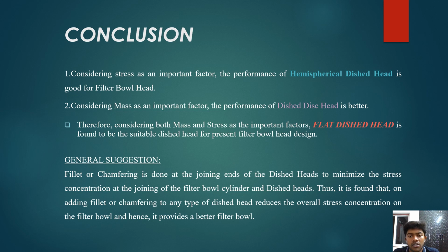So the general suggestion which can be given based on the conclusion above is that filleting or chamfering is done at the joining ends of the dish head to minimize the stress concentration at the joining of the filter bowl cylinder and the dish heads. Thus, it is found that adding a fillet or chamfer to any type of dish head reduces the overall stress concentration on the entire bowl, and hence it provides a better filter bowl for the given filter.